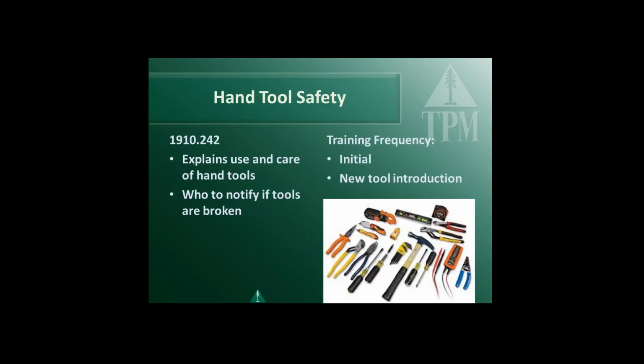So that's combustible dust. Hand tools: basically if you have a hazard, let's say you're dealing with chisels, with mushroomed heads. I've seen citations on mushroomed heads on chisels, a few thousand dollars for a chisel. All you have to do is grind off the ends of them. But have a program, have a way to manage those, or a schedule.